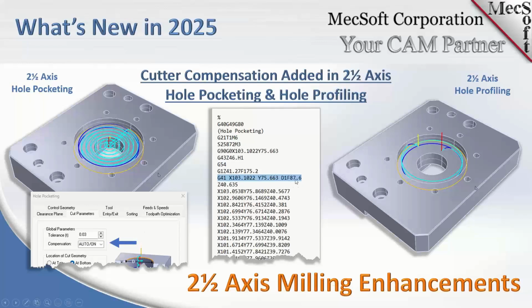When you post, I do want to mention that cutter comp has to be set up in your post in order to output the G40, G41, G42, etc. in your G-code file. If you're posting and you don't see it, just contact us or send us your post definition file, and we'll add those criteria to it and send it back to you.